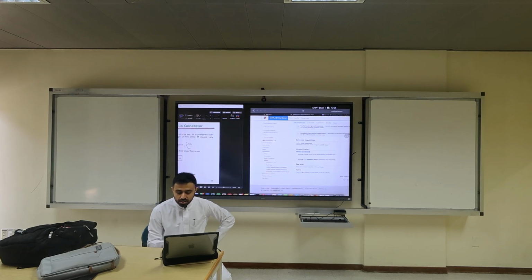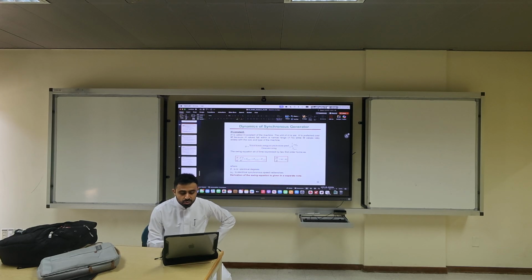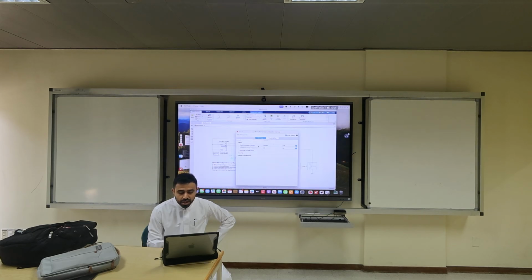Go here, Simulink. What do you see? In inertia, you put a power with frequency or number of poles. Then the inertia constant is 3.5. Is it between 0 and 10? Yes. It's per unit. What are the initial conditions, etc. Go to the description. It tells you what the description is. Now, for one pole pair, the values are between 2.5 and 6. These are the recommended values.